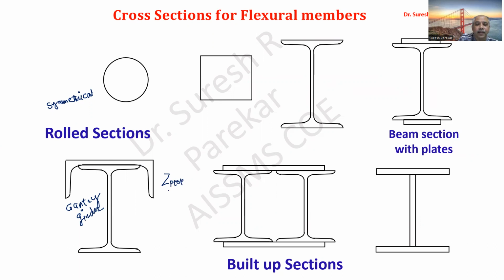Why Zp top more? Because we have lateral and longitudinal stresses in the top flange, and therefore to resist them we require greater section modulus in our top portion, that is above the neutral axis. Then if load is very large and span is very large, that means bending moment is very large, we will go with built up beam sections. And then plate girder, we are already with this in unit number 6.